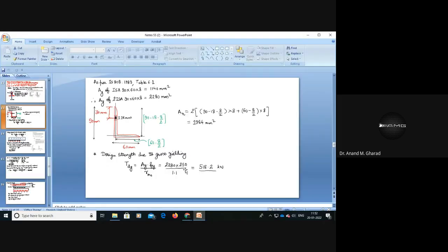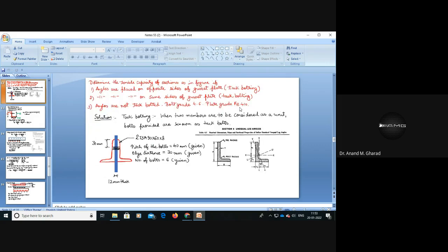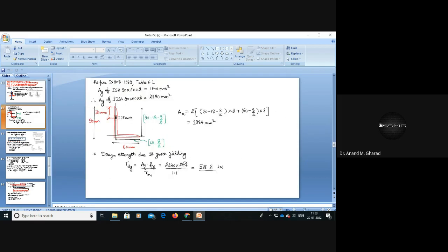It is yield stress, and since we are concerned with the yield stress of this angle section, which is nothing but a steel member, material property steel, please verify Table 1 of IS 800 2007. So please check that. And where do you find this 250 value? I will give you a hint. This is for grade 410. For grade 410, where do you observe this 250 value to be written? वो आप identify करो, ठीक है?